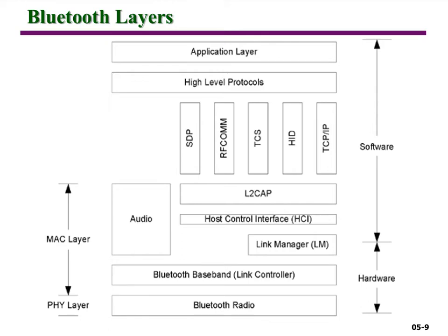So we're still talking about the Bluetooth standard 802.15.1, and we discussed this layer stack last time, and we said that the Bluetooth radio layer corresponds to the physical layer, and it uses the carrier frequency 2.4 gigahertz, and it has 79 different hop frequencies or frequency subchannels that it hops from one of these frequency ranges with a speed of up to 1600 hops per second.